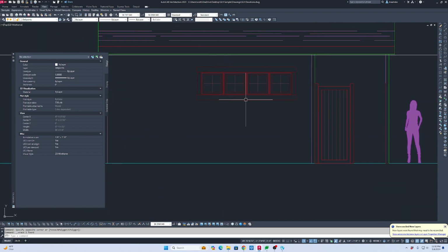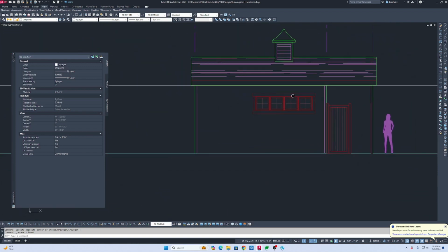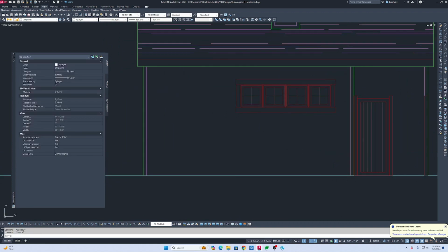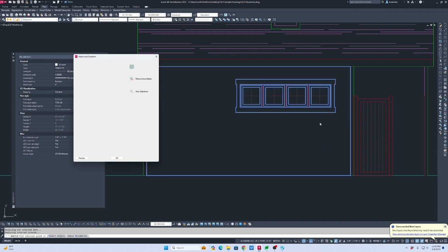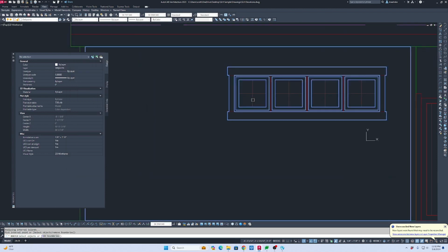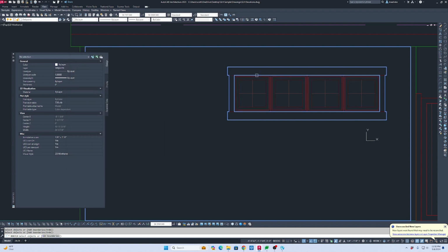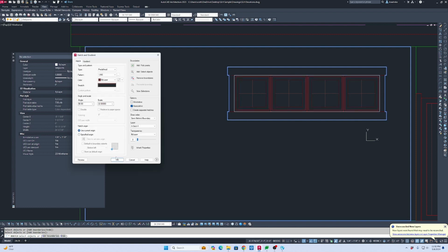So right now, let's just hatch this guy. And let's get rid of him for a minute so I can hatch everything. Oh, I hate the island detection. You could do this and the hatch would come out just fine, but I know from experience that if you get rid of these, it works out much better. Oops, I forgot one. There we go.